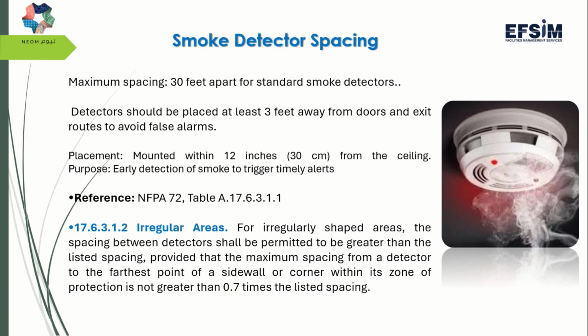Mount within 12 inches from the ceiling. Purpose: early detection of smoke to trigger a timely alert. As reference, table 17.6.3.11.